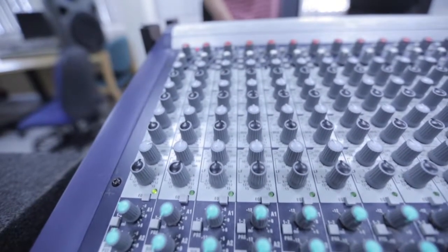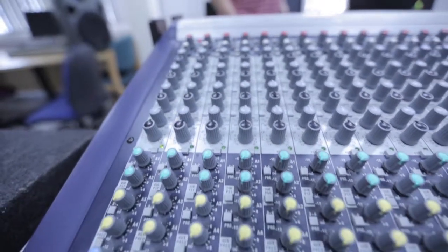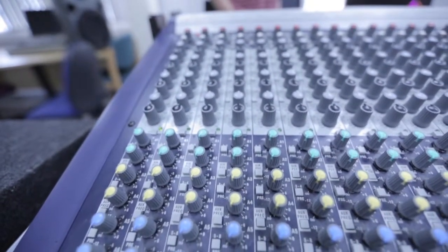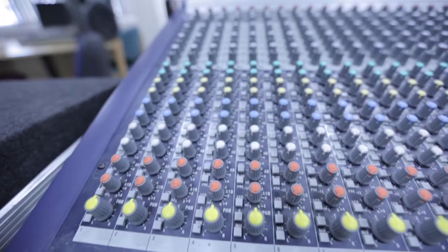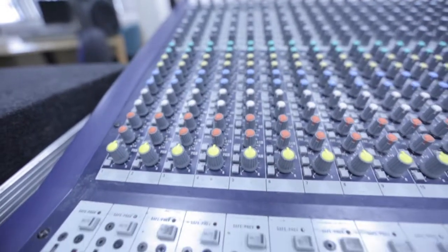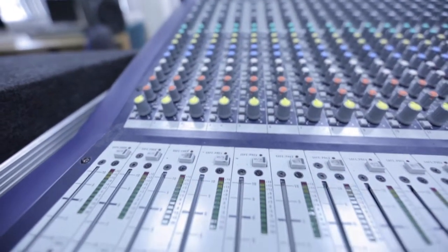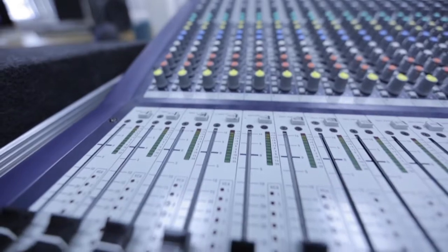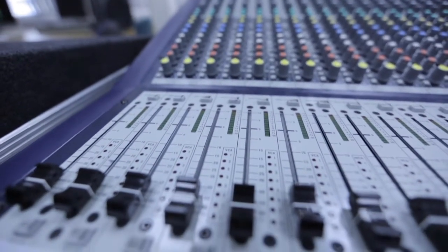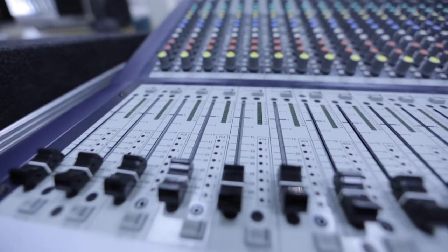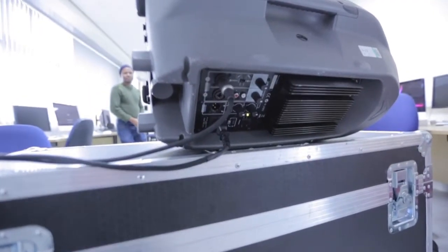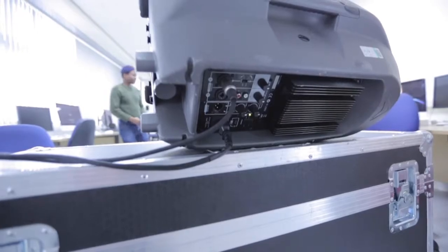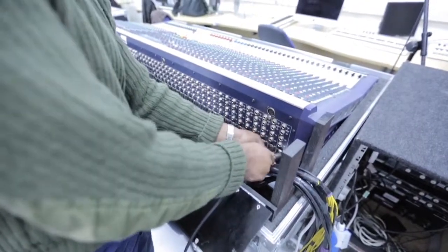Then the signal moves through the auxiliary send section. This allows us to send a copy of the signal to effects and other processing units. These also send the mix to the onstage monitors. That's followed by the channel pan pot. And finally, the channel fader, which determines the amount of the signal to be sent to the front of house monitors, through speaker A in the socket labeled right, and speaker B in auxiliary 4.